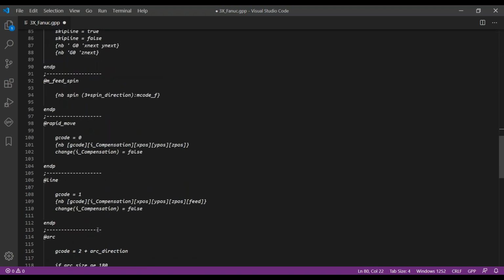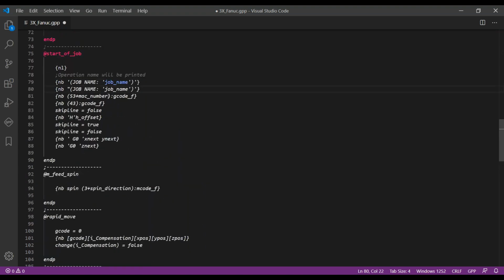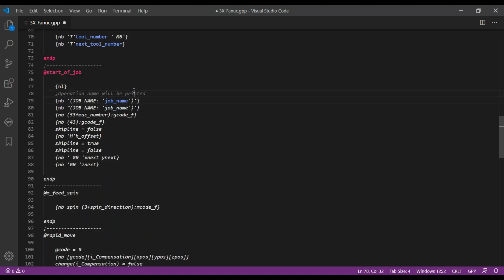So if I follow, let's say, the white line, go up, I can see that this one is colored okay, this is colored okay, this also. So the last white line is the problem. And now we know, because we said here use the apostrophe and here use the quotation mark, it is not registering as a complete syntax. If we save this and try to generate the Gcode, we will get an error.